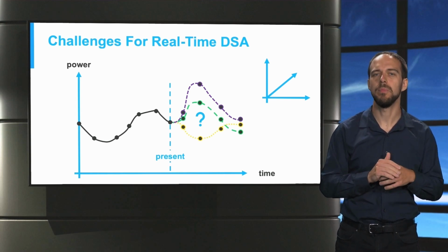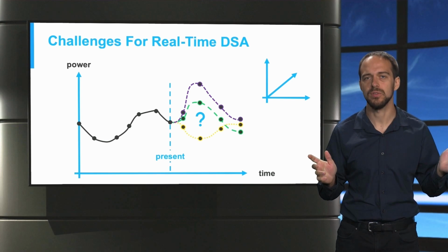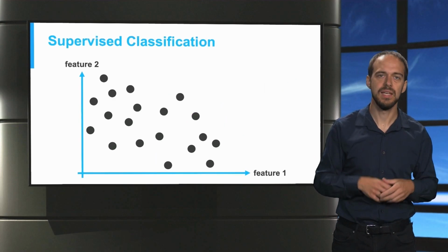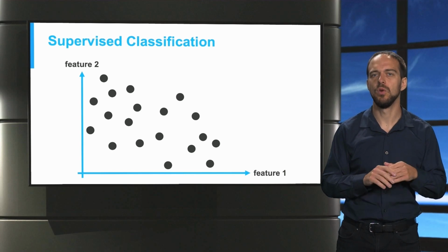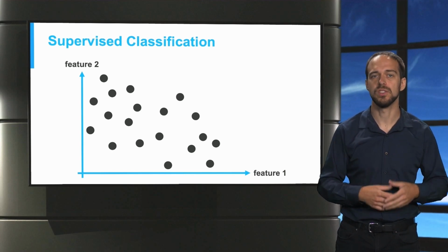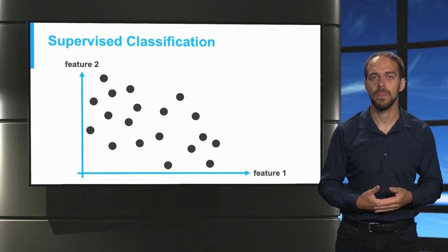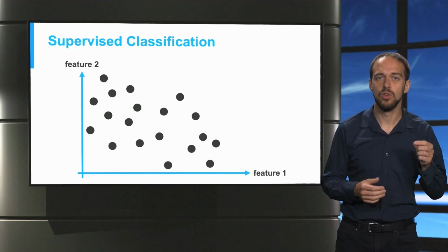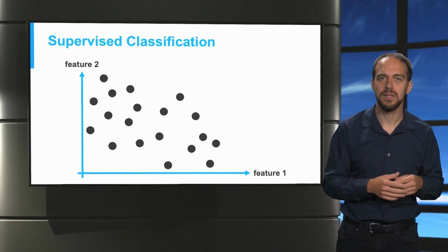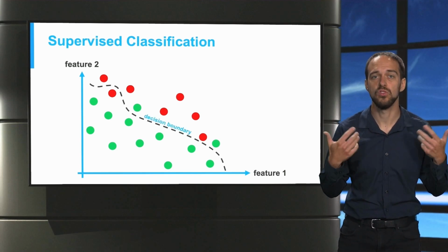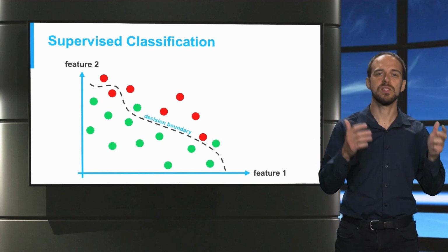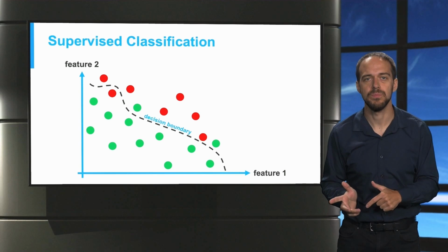So how can we manage to analyze such large amounts of data? Supervised classification represents a promising set of methods to avoid analyzing all of these operating conditions with real-time simulators. The idea is to train, long before real-time operation and based on secure and insecure conditions, a classifier that can classify or separate security from insecurity.